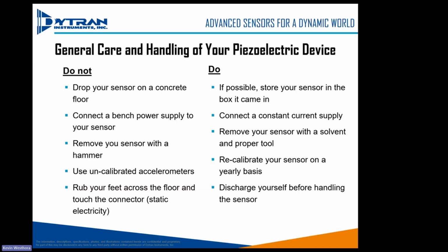And it's always important to understand that these are electrostatic sensitive devices. We ship them in electrostatic protected bags, but it's always important not to touch the pin of the connector unless you're grounded. Okay, so that's always a good reminder. All right.